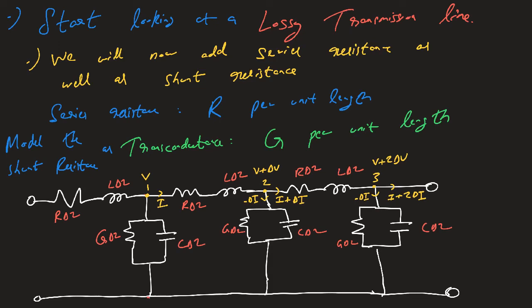Let's say with your headphones, you usually have a red wire and a black wire. The red wire usually carries signal. The black wire is the reference or ground, and they usually have a cladding or insulation around them. If you remove the insulation and the red and the black wires touch, you have a lot of current going from here to here. You basically short your transmission line. You don't hear any music in your iPhones or whatever it is you're listening to.